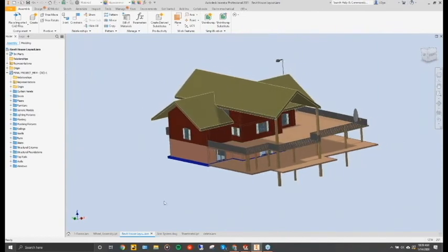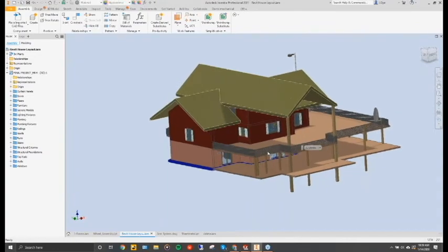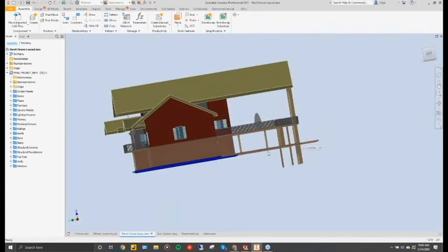on that Revit file. Again, if the vendor or customer makes a change to this house layout, this Revit house, I will then see that lightning bolt in my quick access toolbar up here become selectable. So I'd select that, see what change gets updated in my design, and then I would maybe need to adjust that support pole holding that roof extension up there.